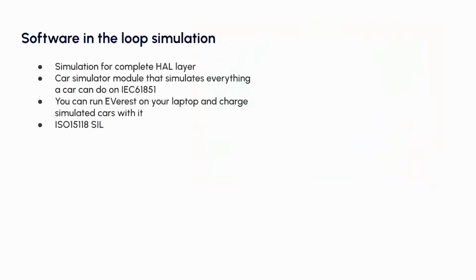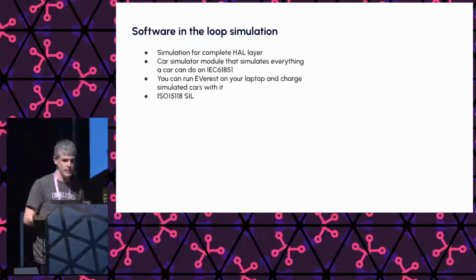What's interesting as well, we have a complete software-in-the-loop simulation, so the hardware abstraction layer I was talking earlier about. For each of the hardware drivers, there's also a software simulation module available, so that basically you can run the whole EVerest stack just on your laptop without any charging station or a car. And you can also load a simulated car module that you can attach to those simulated charging station modules, and you can run full charging sessions, including ISO 15118 support, and basically develop EVerest and run simulations, and can do fully automatic testing, for example.